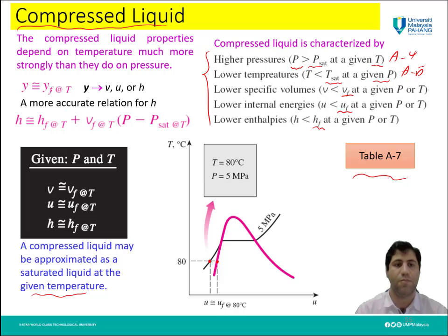So we can simply approximate that these properties V, U, or H, specific volume, internal energy, or enthalpy, are equal to those properties for saturated liquid at the given temperature.